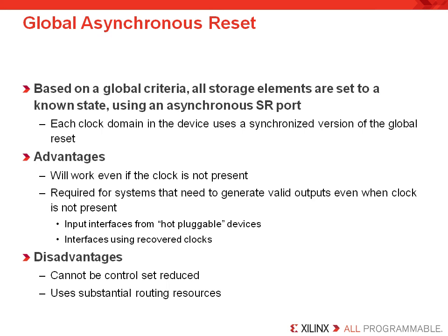The advantage is it will work even if the clock is not present. It's required for systems that need to generate valid outputs even when the clock is not present, such as input interfaces from hot pluggable devices and interfaces using recovered clocks. The disadvantage, of course, is it cannot be part of a control set reduction. Since it's ported directly to the flip-flop port, this is often greatly limiting to the control set utilization in your design. And it also, like a global reset, will use substantial routing resources. So in general, global asynchronous resets are not encouraged as well.